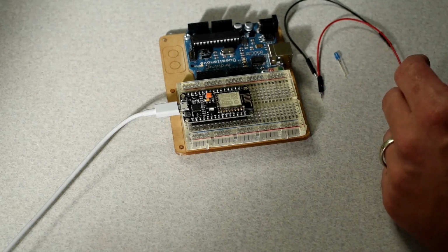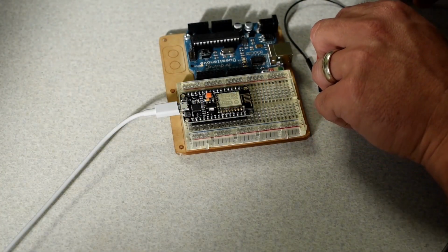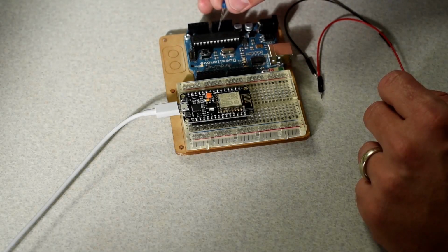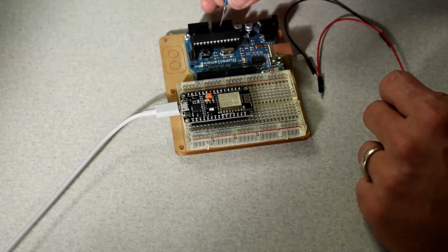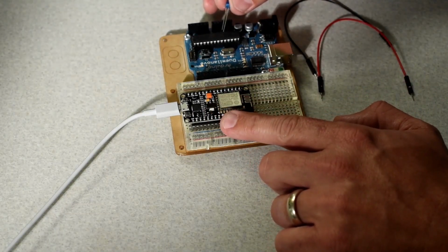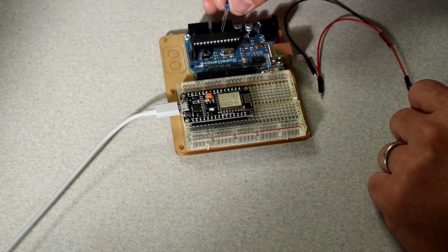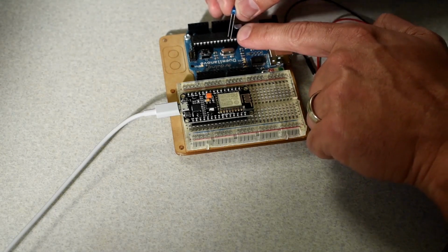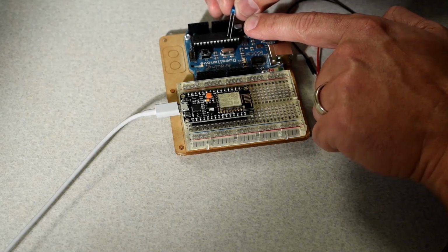Since we're here and we're actually already looking at the board itself, let's go ahead and just program up the hardware component of this video. Super, super simple. It's 3 components and that's it. What we're going to basically do is we're going to take an LED. Now, on an LED, if you don't have any microcontroller experience whatsoever, you'll need to know that some LEDs operate at different voltages. This particular one works perfectly, no resistors necessary right off the voltage of this board. But you'll notice that there's a long pin and a short pin here. Now, the long pin is supposed to connect to the positive lead.